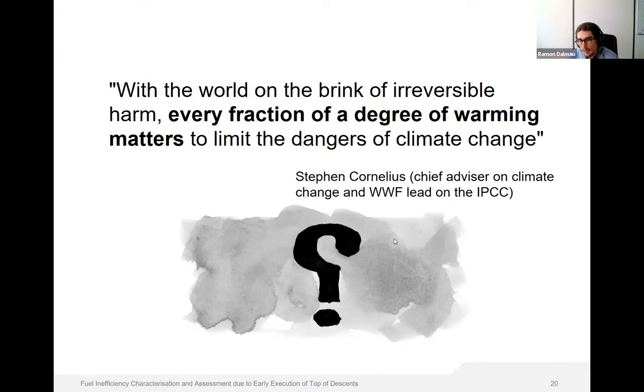And it's true that we think that ATC could try to respect the top of descent as much as possible, but of course, in order to respect the top of descent, they need to know the top of descent. So I don't think pilots should send the top of descent via communication. No, maybe it could be included in the ADS-B data, in the broadcasted data, in a more automatic way, not through radio communications.